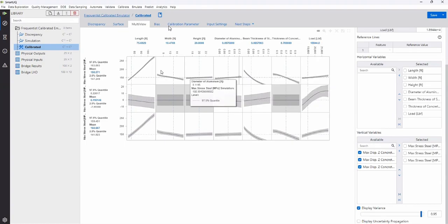You pick the right parameter values in the simulation, and you get a simulation that tells you exactly what happens in reality. But we can look at this and see that as we increase this parameter, as we increase the loading that we're applying to the bridge, our discrepancy model is predicting a larger and larger value. This basically means that as we increase the load that we're simulating, there's something in our simulation that makes the result increasingly underpredict what happens in reality.